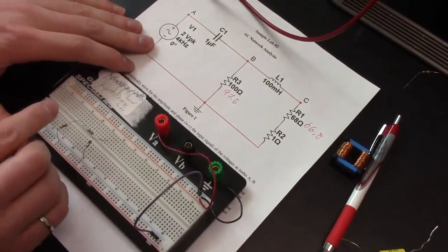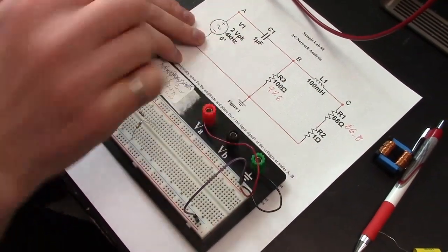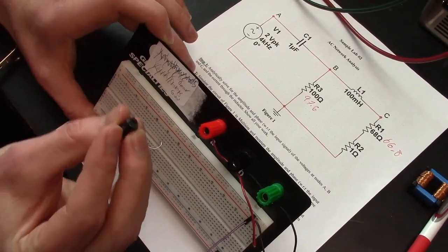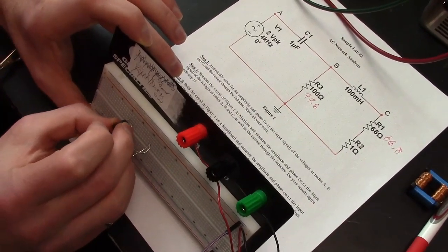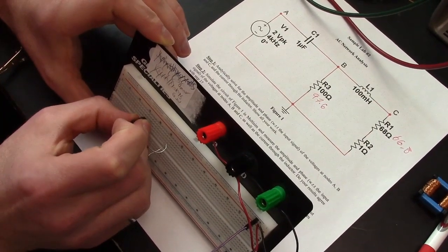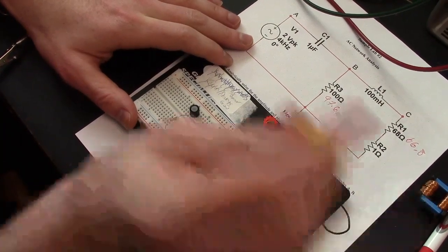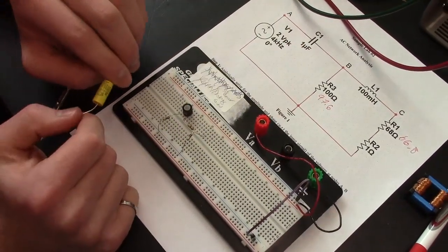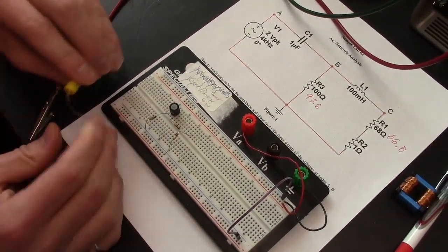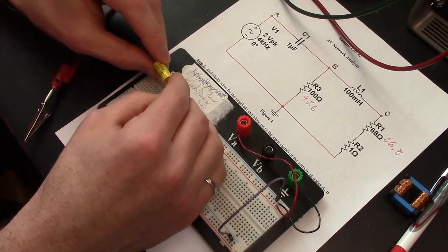So we need to connect that across the top of the 68 ohm and the top of the 100 ohm. So we'll do that on the breadboard like this. The probes are the right spacing to fit a little bit apart with a gap of just kind of one between them. So we'll put that in there. And then we can connect the 1 microfarad capacitor from that junction here at B to the positive terminal there at the top. So we'll do that.